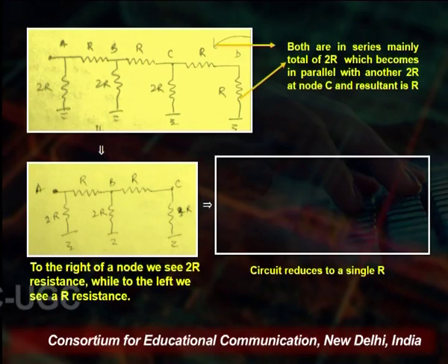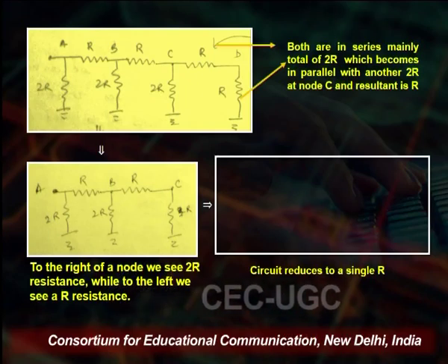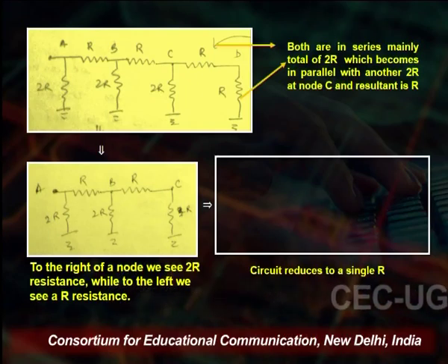For example, we need to understand whether we need a DAC for a disc jockey, a DJ, for a DJ performance. For a DJ performance, I would require a DAC that handles high current, because we play music on large speakers and the driving current over there is quite high.